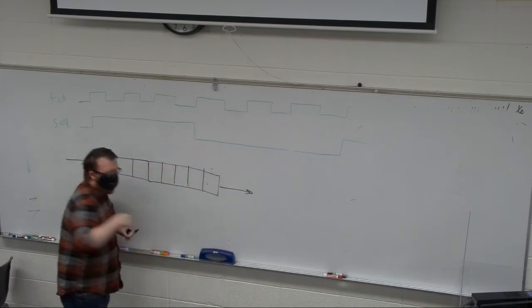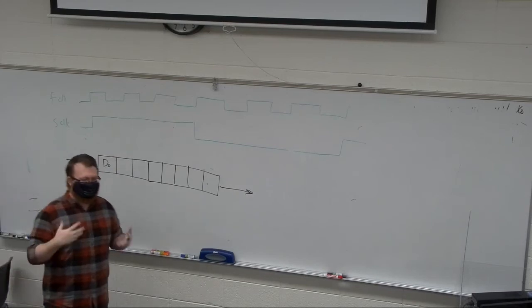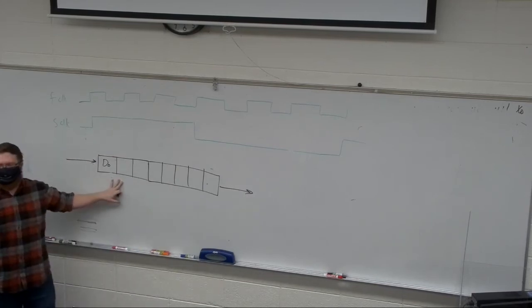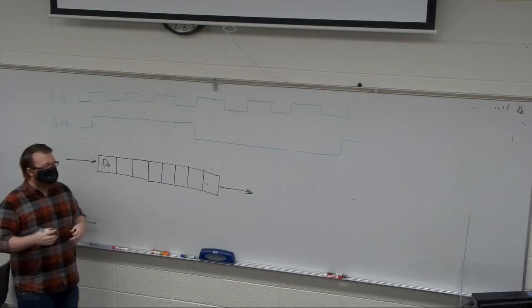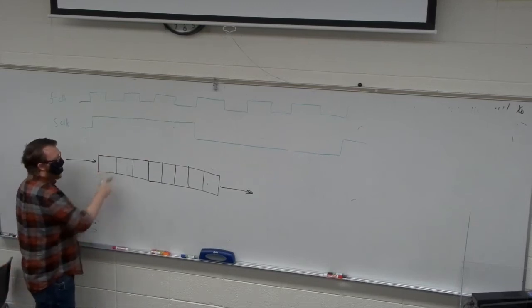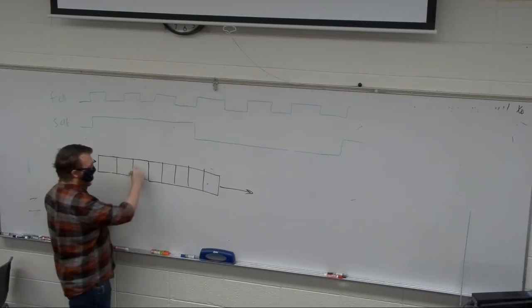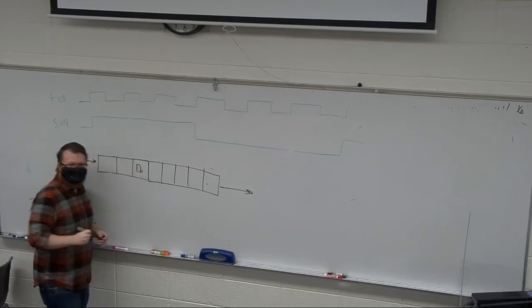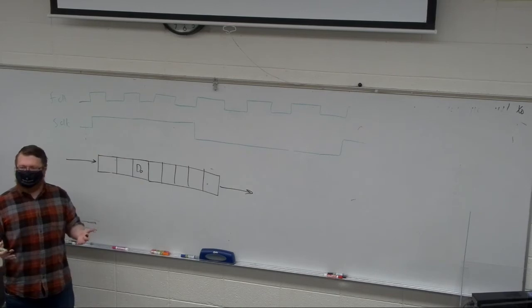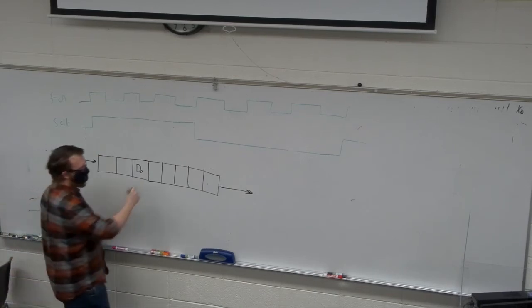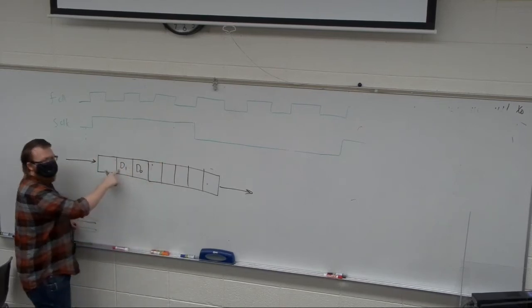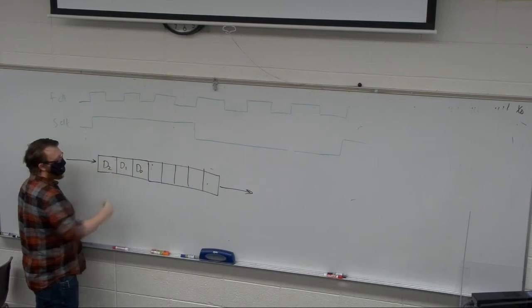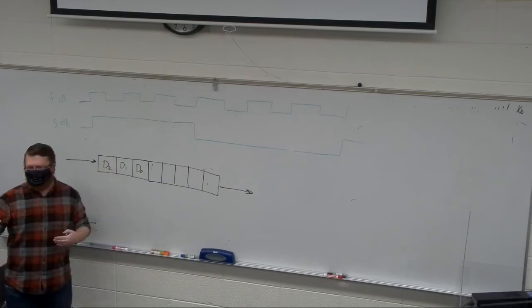And the FIFO is going to have, well, we'll start off with 2 different flags. You could also call them pointers: a read pointer and a write pointer. So this one says, let's write at 3. Okay, so then I would go ahead and increment my write counter and write the next bit in, call it D1. Then we're going to write the 3rd bit, D2. So I've written 3 bits and now I want to start reading.